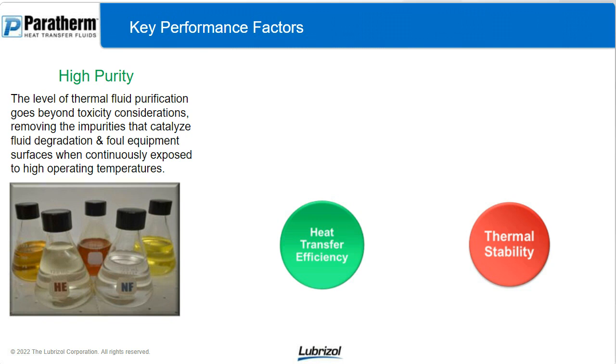Pay attention to the SDS. Look at the colors. Usually with especially a mineral oil-based product, the purity level can really kind of be indicated by color. A lot of color, a deep yellow or an amber, an orange, straw colors, anything that's really tinted with color is going to show one or two things. Either way too much additive has been put into that formulation that's unnecessary and going to cause problems, or the fluid itself was not taken to purification levels and distilled out in its production phases.